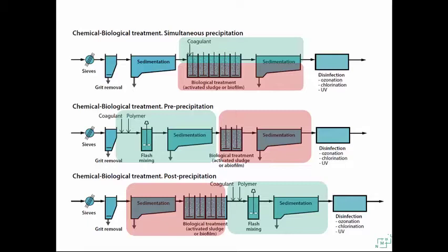Generally in continental Europe, they have built mechanical and biological treatment plants, but in Norway and some of the Scandinavian countries, we built mechanical chemical plants. Because in Norway, the target was to remove phosphates mainly, and in continental Europe, the target was to remove organic matter and later on nitrogen. But now, due to the European Union's urban wastewater directive, we have to remove phosphates, nitrogen, and organic matter. We have to supplement these processes, which means that most treatment plants in Northern Europe have all three processes combined now.